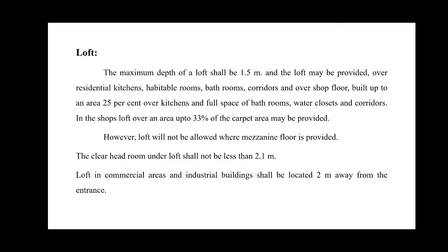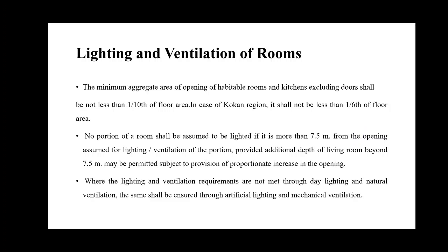However, it should be noted that loft will not be allowed where mezzanine floors are being provided. The clear headroom under the loft shall not be less than 2.1 meters, and loft in commercial areas and industrial buildings shall be located 2 meters away from the entrance.